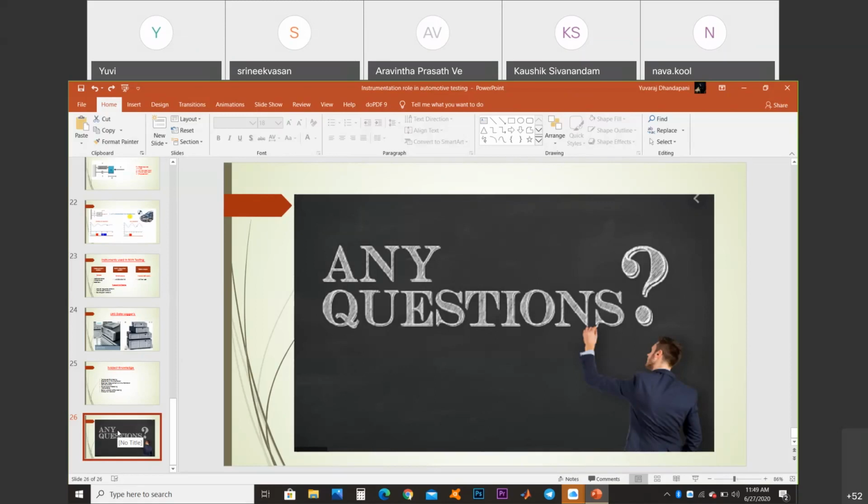Say, for example, if you want to measure the vibration data in the engine, in the injector. Let's take an example like this. So I'm going to mount the accelerometer near the injector. Whatever data I'm going to collect from the sensor is time domain data, time versus amplitude. But the important thing is that it is raw data. We call it raw data because it's a combination of many signals. So in post processing, whatever data you collect in data acquisition is raw data.